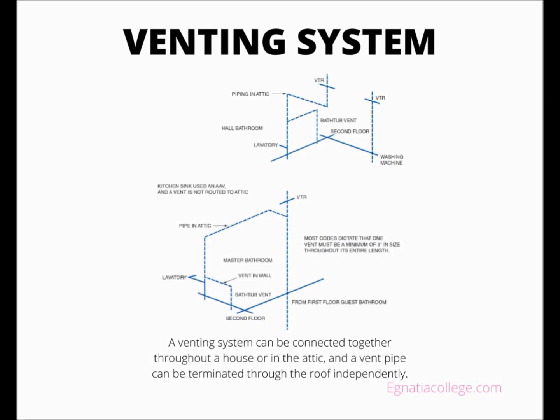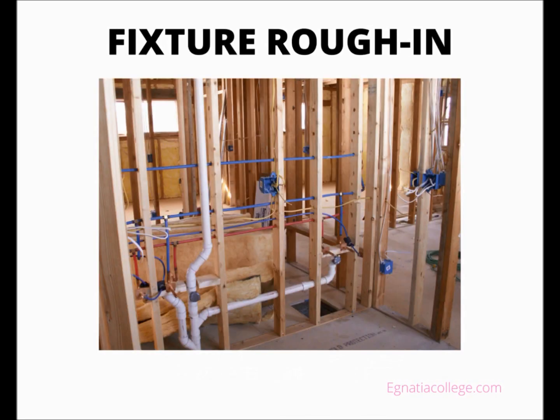A plumber uses a level to align the pipe with the angled slope of the roof, and then draws an oval line to indicate the cut area. A hole can be drilled, and a reciprocating saw used to complete the cut, or a plunge cut can be made using the saw blade at an angle. The vent pipe is installed through the roof, and a plumber or roofing contractor installs the vent flashing on the roof. A roof sealant is placed under the flashing, and galvanized roofing nails are driven through the flashing and into the roof plywood. The most common type of roof flashing is made with neoprene. The center portion where the pipe passes through is flexible and conforms tightly around the vent pipe.